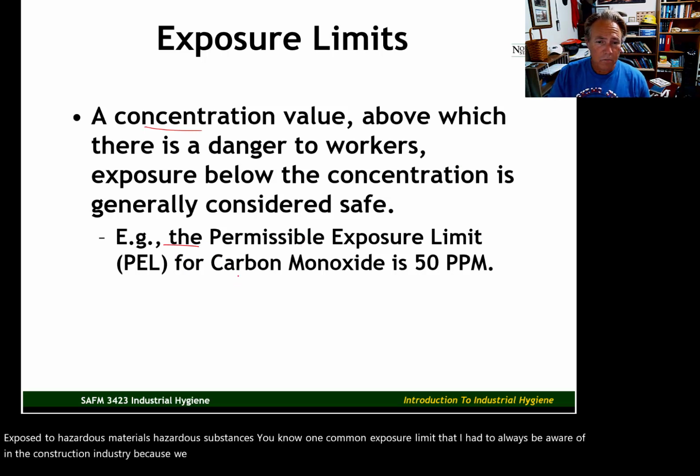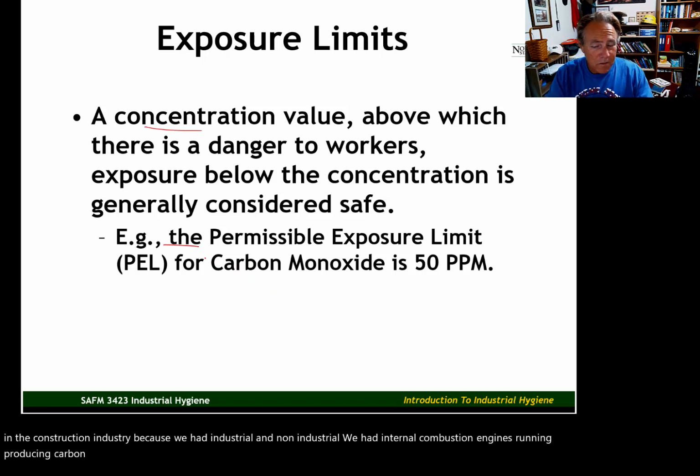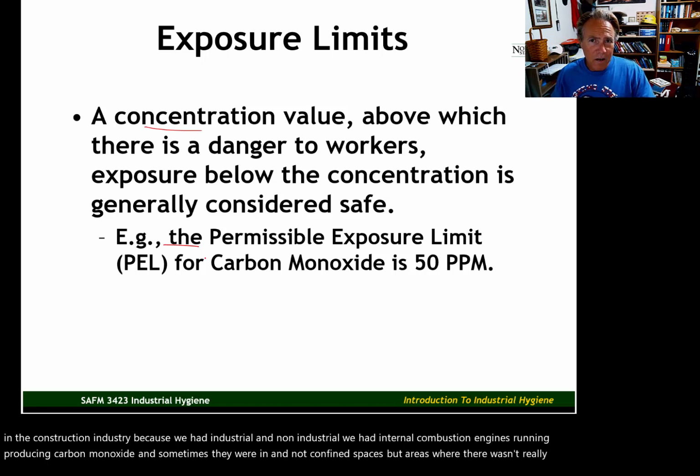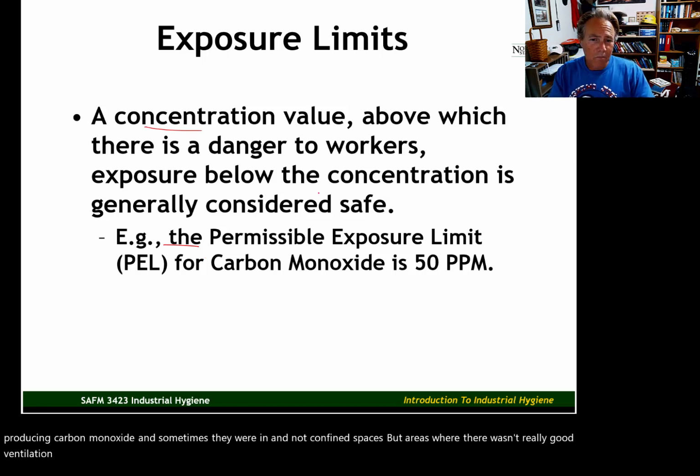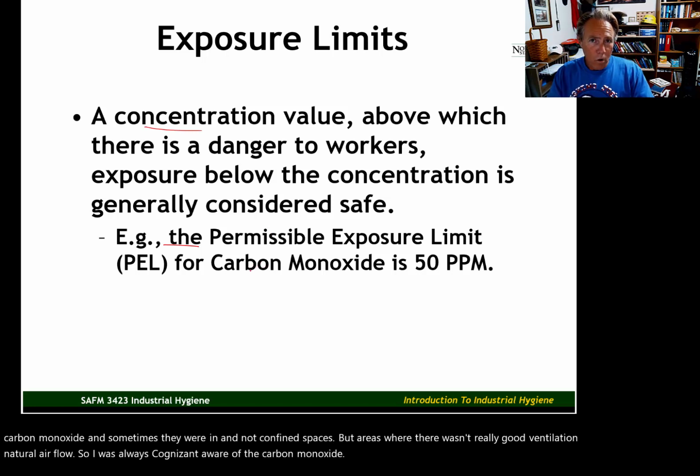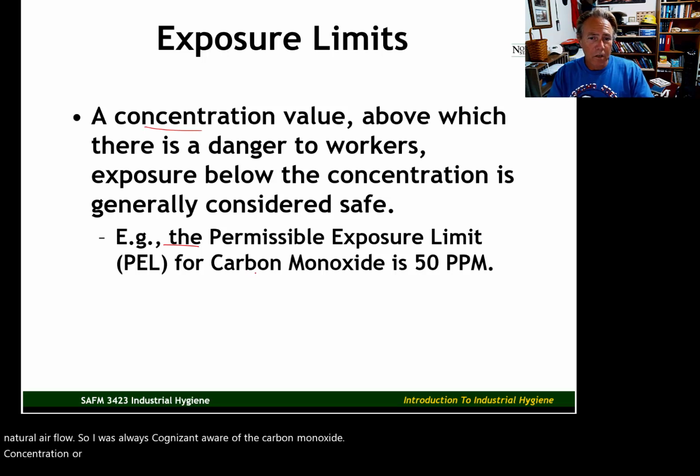One common exposure limit that I had to always be aware of in the construction industry, because we had internal combustion engines running, producing carbon monoxide, and sometimes they were in not confined spaces, but areas where there wasn't really good ventilation, natural airflow. So I was always cognizant, aware of the carbon monoxide concentration. Our workers wore sniffers that would continually measure the carbon monoxide level in their work area.